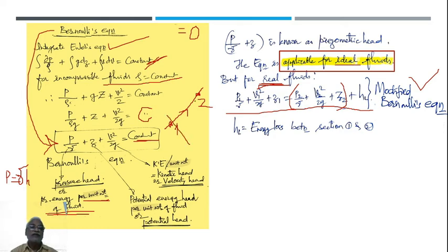You can call it a section or point. It is along the flow. You have to choose a reference section 1 and section 2, or point 1 and point 2 in the motion. So obviously downstream end means after some flow the energy will be a bit less because the head is lost. So this is Bernoulli's equation. I think with this we'll stop. Thank you.